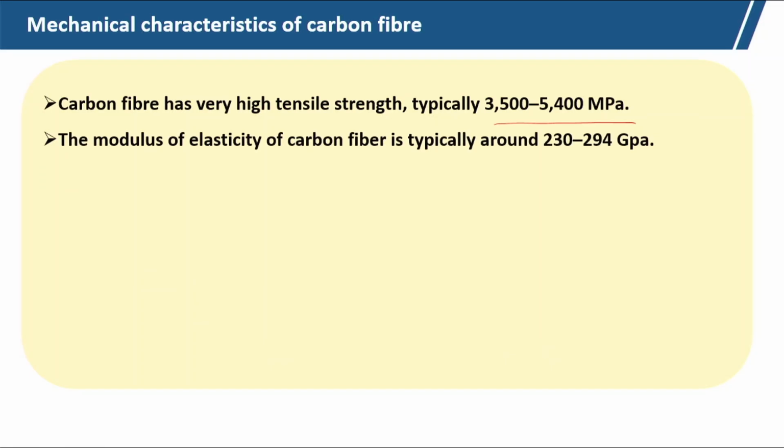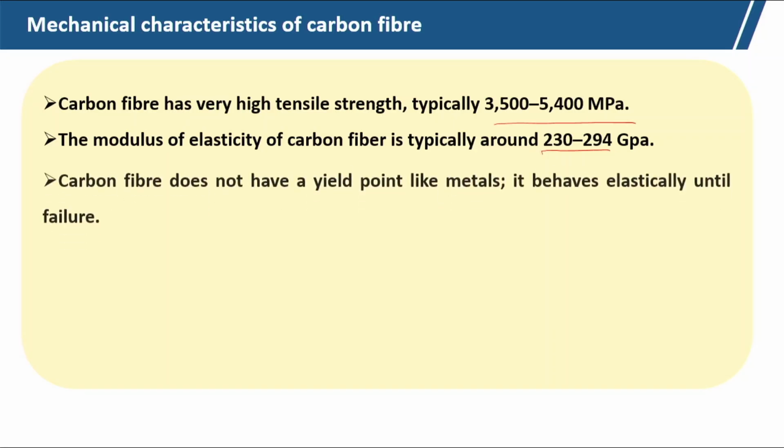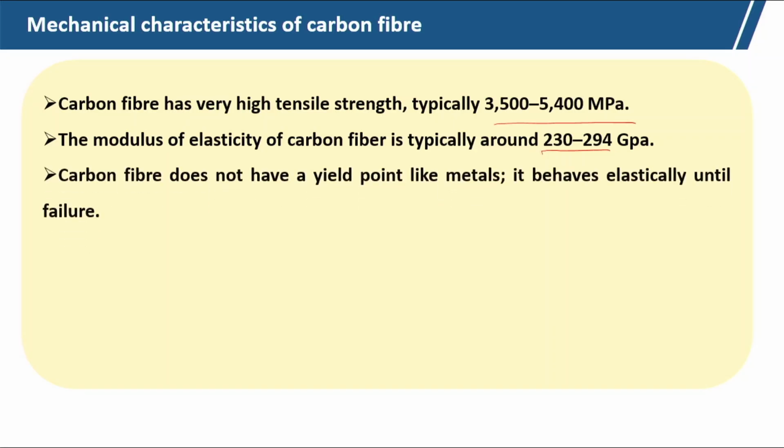The modulus of elasticity of carbon fibers is typically 230 to 294, around 300 gigapascal, which is very high, and it does not have any yield point. So it behaves like an elastic material.